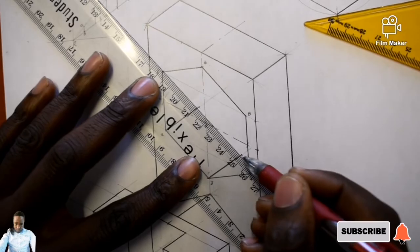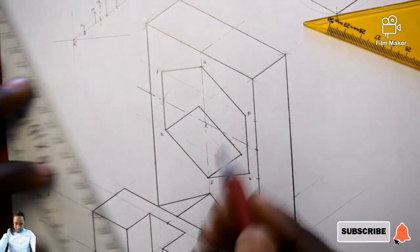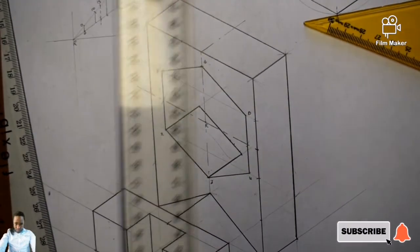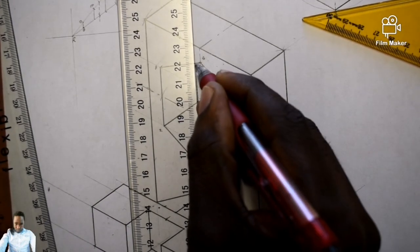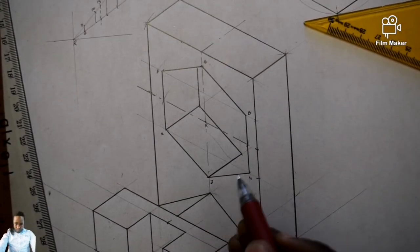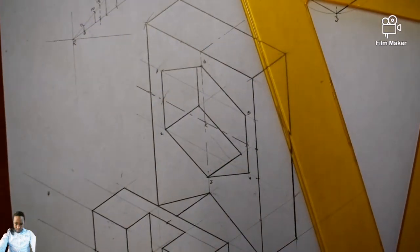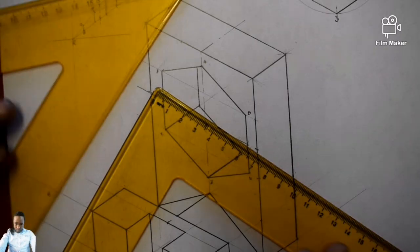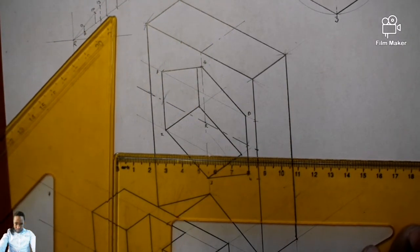3, which is this one. There you go. So a line that's going to be parallel to 1 2, the point of 1 2, which is going to be vertically up from here to right there. Then another one that will be parallel to this one. So simply use the 2 set squares of mine. The other one I will pretend, I'll treat it as a T-square. So like this, there we go. Just push it like this.